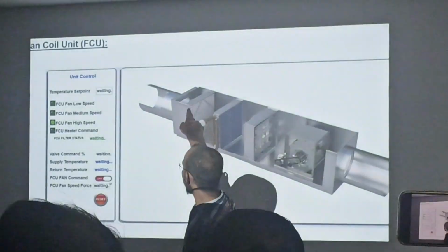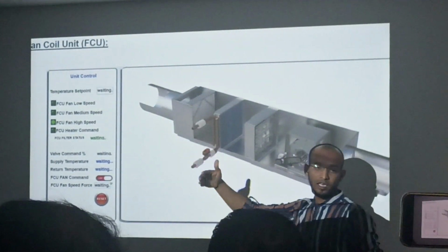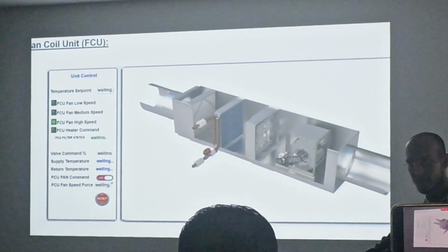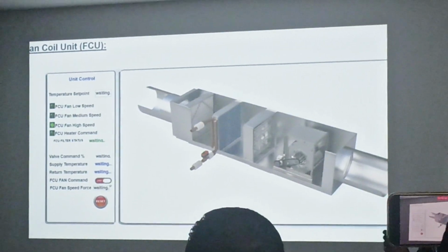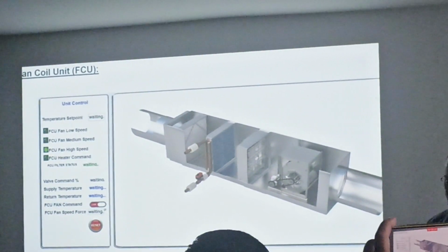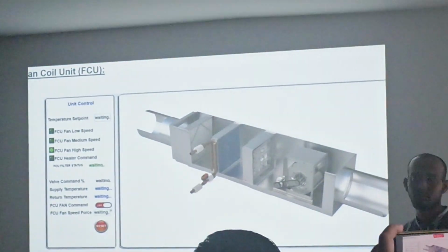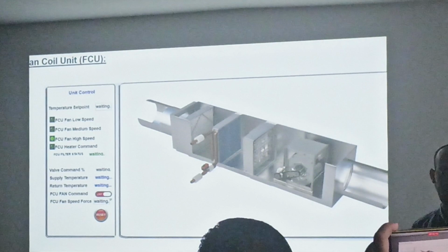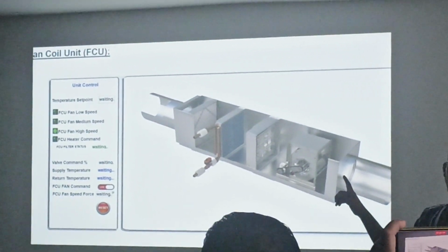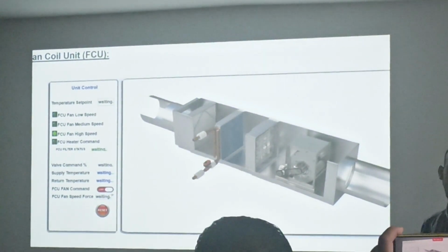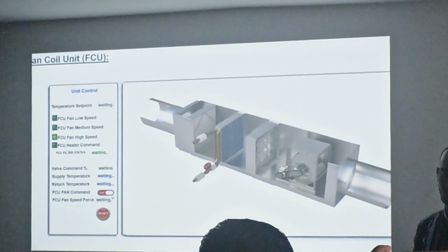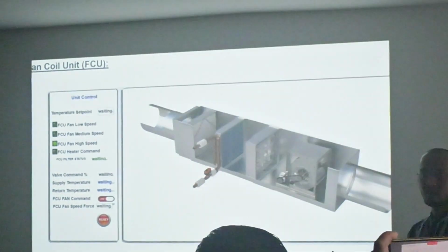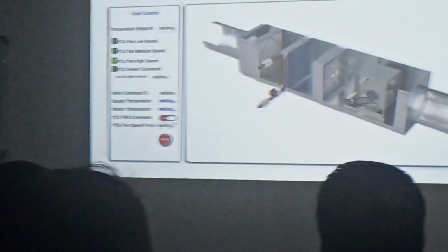There is also a filter available in the FCU, an incoming filter. There is a DPS placed between the filter and outside air, and whenever the filter gets dirty, you will see a dirty alarm. How many types of filters? Here we have only one digital based DPS and only one filter, not a pre-filter and back filter. That applies to the AHUs, not the FCU. In the FCU you will find only one filter in this project. Different projects have different kinds of filters.